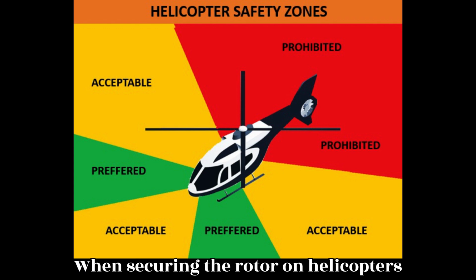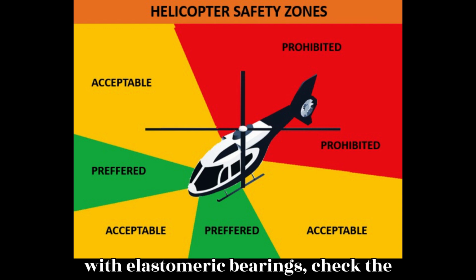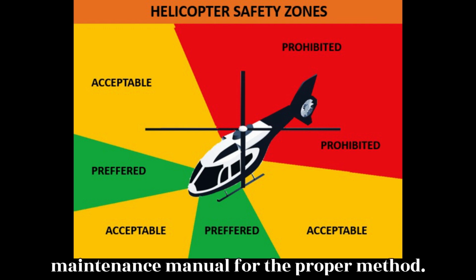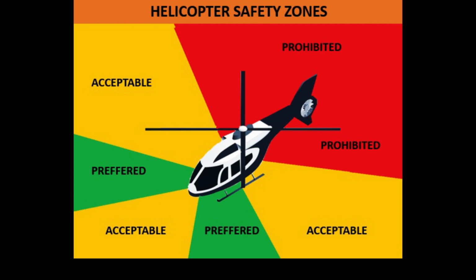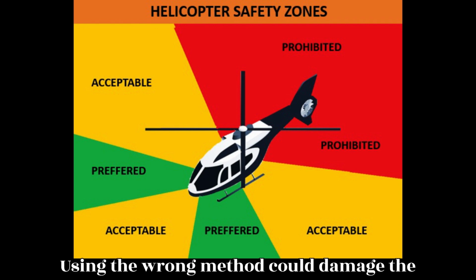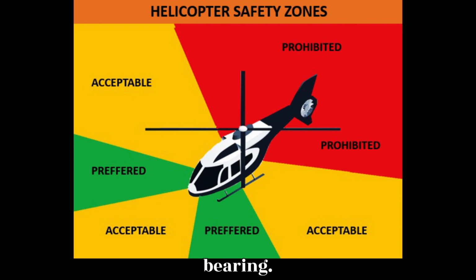When securing the rotor on helicopters with elastomeric bearings, check the maintenance manual for the proper method. Using the wrong method could damage the bearing.